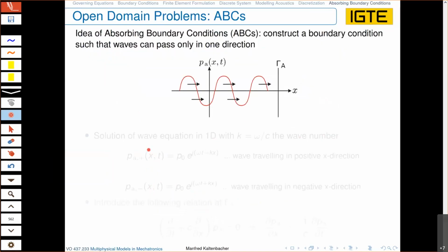Okay. A very important property for all wave propagation, it's the same also for electromagnetic waves, and clearly here, as we discuss acoustic waves, is so-called open domain problems. You always want to restrict your computational domain just to such a domain where we are interested in computing the acoustic field, and we are not interested in making it larger and larger. But if you have free radiation, what to do at the limiting computational domain?